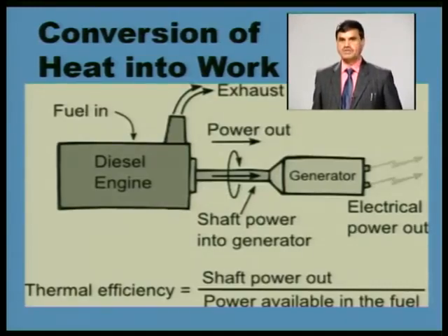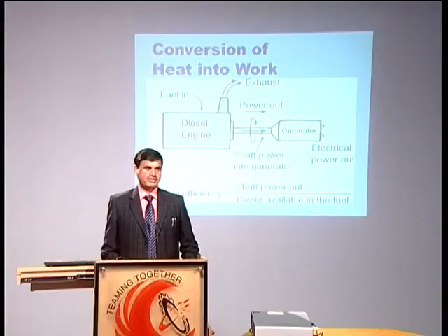Normally, the value of this thermal efficiency for a petrol engine is around 25-26%. In the case of diesel, it may be up to 30%. The meaning of this is that of the input we have given, in the case of diesel only 30% is converted into useful output. If it is a petrol engine, the spark ignition engine, then the conversion efficiency is 25-26%, and the remaining heat goes as waste.